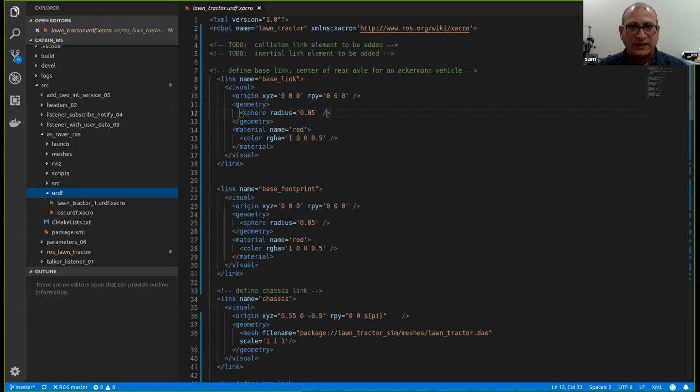One thing you have to make sure of is that if you're defining any of the dimensions over here, everything is in meters. This is the most important part to remember, because sometimes your model is in either inches or mm, so you have to convert that into meters. The radians part is really easy. You have to define angles in radians, but there's a quite convenient dollar construct that would define the angles for you in radians.